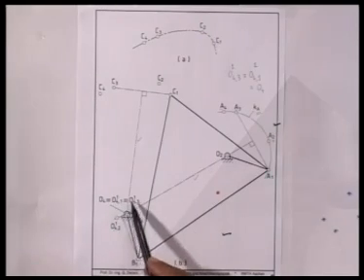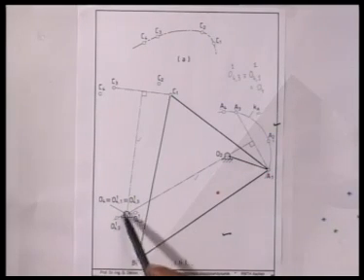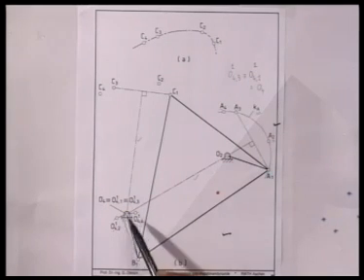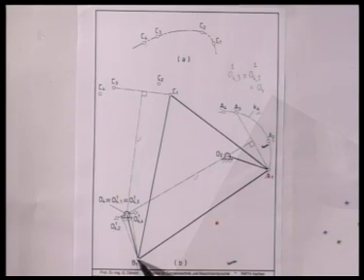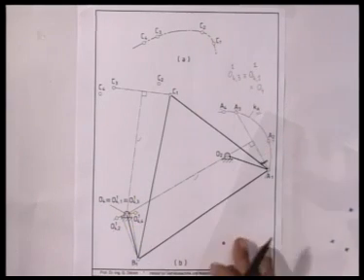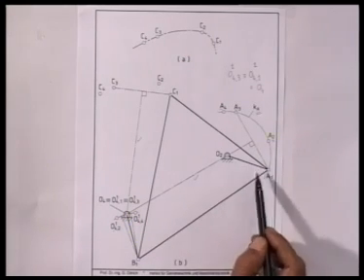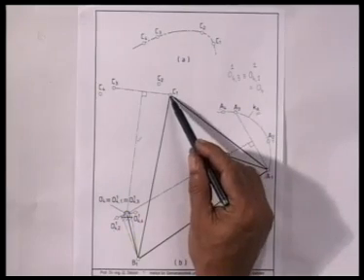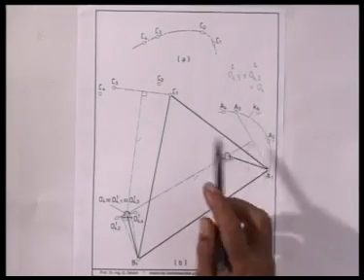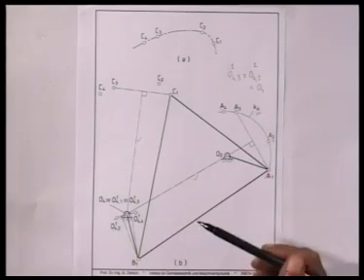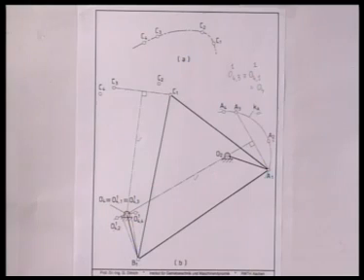So 2 of the 4 inverted positions coincide. So 4 inverted positions give me only 3 distinct points, and I can always draw a circle through these 3 points, and the center of the circle is determined here at B1. So now I get the 4R linkage function path generator O2, A1, B1, O4 with C1 as the coupler point. Once this linkage is moved, this point C will go from C1, C2, C3 and C4. So we have got a 4 position synthesis path generation problem solved by using the point position reduction technique.